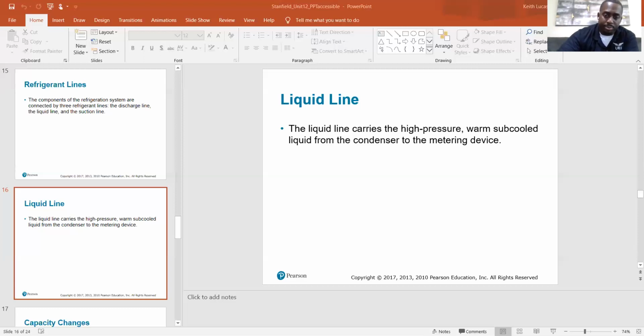We've got some hot vapor here, we've got some cold liquid here, and this one is a perfect environment to remove some heat. This is the perfect environment to absorb some heat. That's all this refrigeration system is designed to do. Absorb heat here, remove it here. And as we absorb heat, the air coming out of the other side is nice and cool, making everybody comfortable.